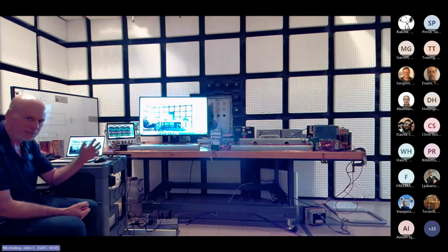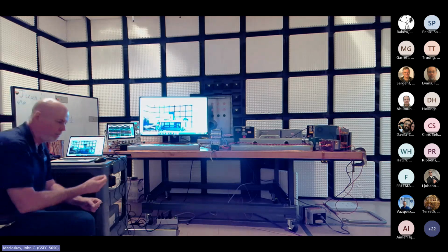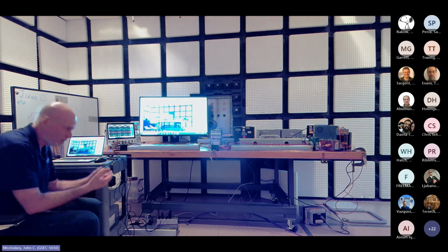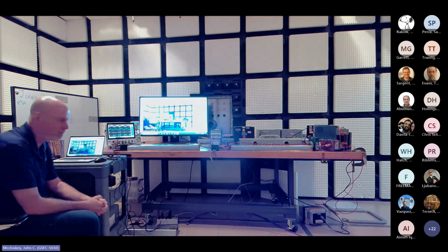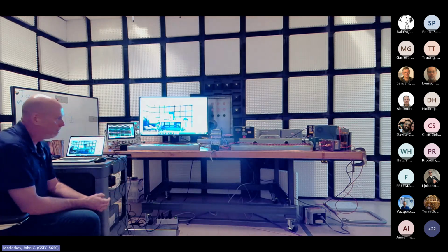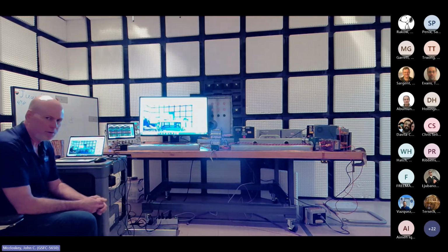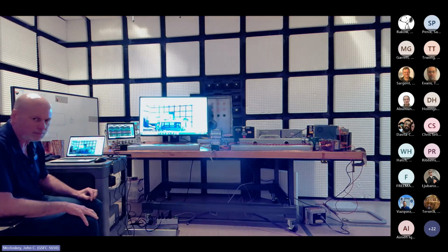So that means that 300 number you put in the numerator, that 300 divided by the frequency in megahertz, you can't use that anymore. It's something lower than 300. Again, 300 is representing 3 times 10 to the 8 meters per second. It's 300 megameters per second divided by frequency. That's where that 300 divided by frequency in megahertz comes from. So once you put that absorbing clamp in there, that 300 number is no longer the one to use. I'm not sure what that relative permeability of that stuff is, but I know it's not 1. It's got to be something greater.